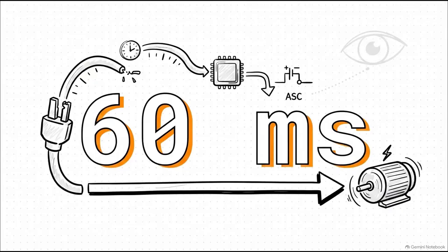And here is the kicker. 60 milliseconds. Under the ASIL D safety architecture, 60 milliseconds is the absolute maximum fault-tolerant time interval, or FTTI. From the exact microsecond a physical pin loses contact due to fretting wear, the system has to filter out the noise, realize it's a real failure, cross-reference the dual-core lockstep, and execute that complex active short-circuit fallback. If it takes 61 milliseconds, the torque surge could cause the vehicle to lose control.